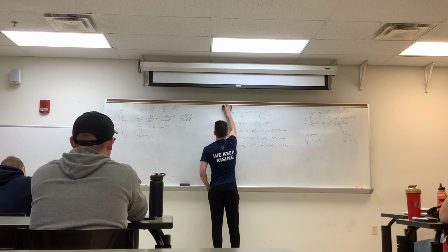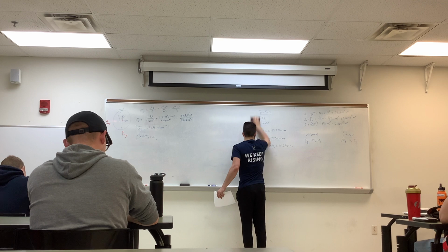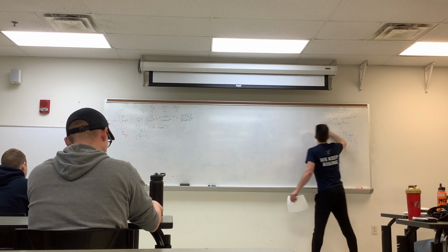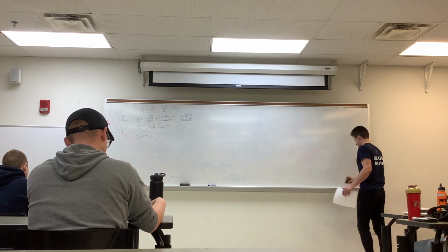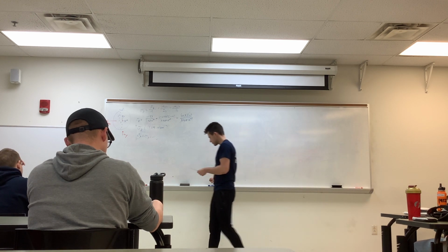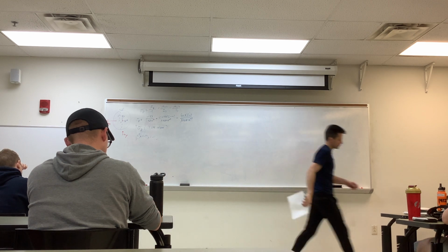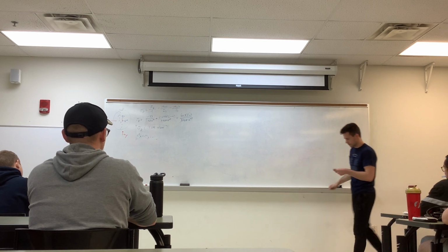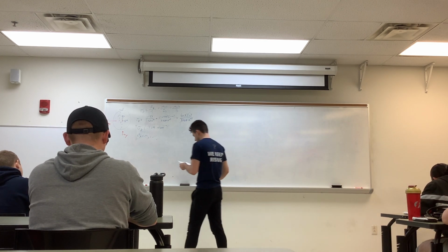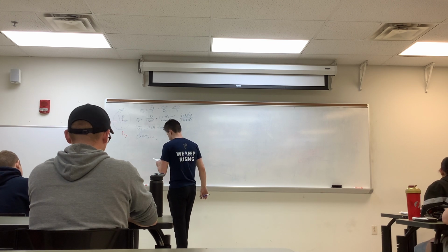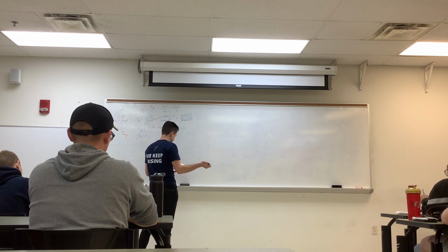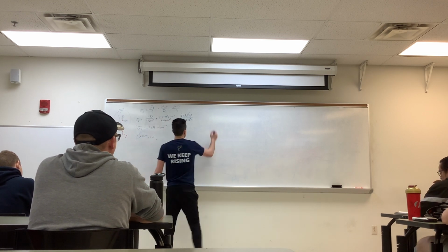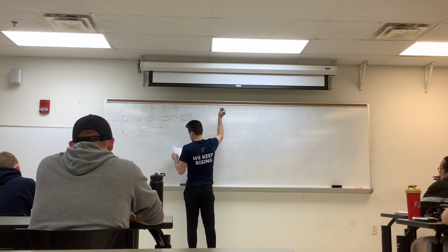So going on to shear next. Make sure I have everything written down from that. Yep, so I have all our stresses. So going on to shear stress, we have our three separate shears: our torsion and our two transverse shear stresses. I'm going to start with F of x, that just kind of makes more sense.